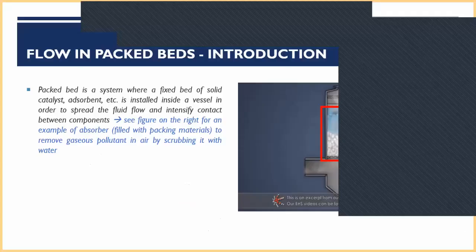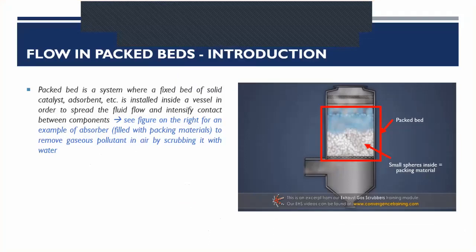Okay, so we'll move now to the third subchapter, which is the flow in packed beds. So the packed bed. I think this is a new term for you. A packed bed is a system where a fixed bed, or a packed bed, of packing materials, which can be a solid catalyst or an adsorbent or others, is installed inside a vessel in order to spread the fluid flow and intensify the contact between components.